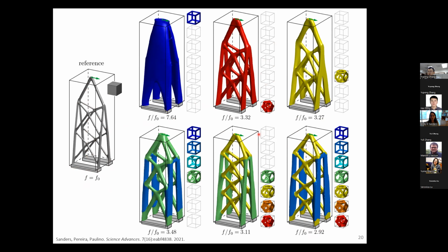And there are a few reasons for that. The main reason is that by limiting our optimization to choose from these specific architectures, we're sort of putting some additional constraints on our problem, right? Each of these architected materials has certain directions of high stiffness and other directions of not so high stiffness. And so the directional stiffness of these architectures dictates the orientation of the members in the final design. Not only that, because these things are porous, we're potentially moving material away from potentially more optimal regions.